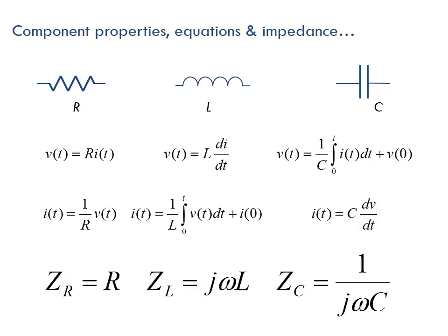In the middle here we have L, our inductor symbol. For the inductor, the voltage is going to equal L, the inductance, times di/dt, the change in current over the change in time. Again, it's storing some energy in its magnetic field, so when you unplug it, some of that current comes out. That's based upon time, and that's essentially the equation for an inductor. You can store a magnetic field in the inductor, and it's a function of time, so it's not immediate. It takes time to fill that magnetic field, and it also takes time to reduce as the field comes out, even if something's unplugged.